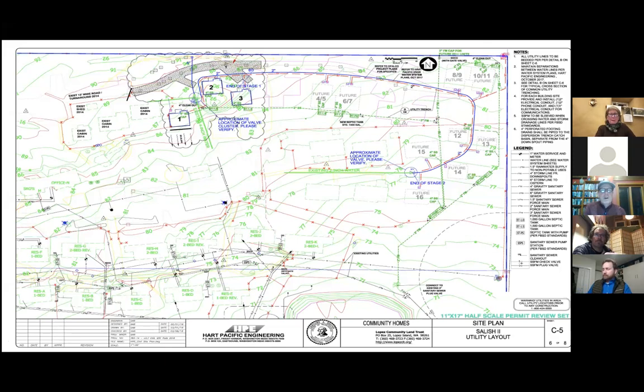You want to keep ditching as efficient as possible. So a lot of times, if you have a photographic record of what's in the ditch and at what depth, that adds to your as-built collection. And it always does come up later that you're trying to find something. So it's crucial. Yes, that's an excellent point, Pete.